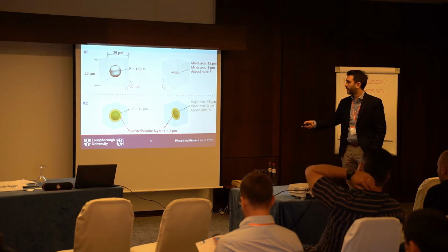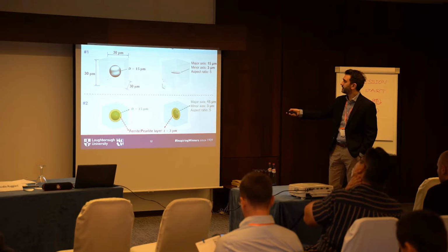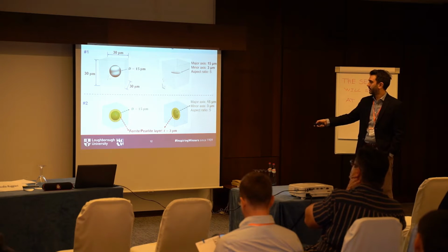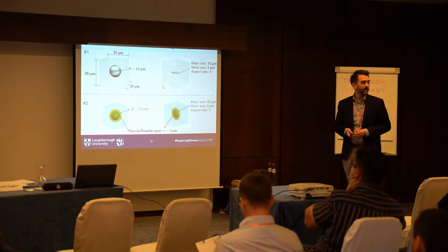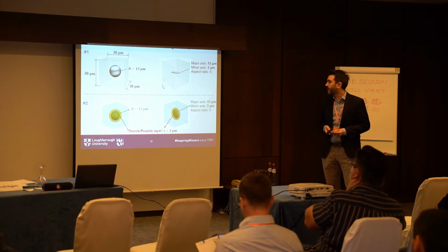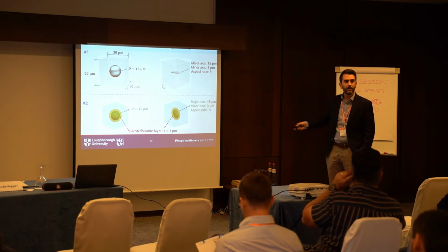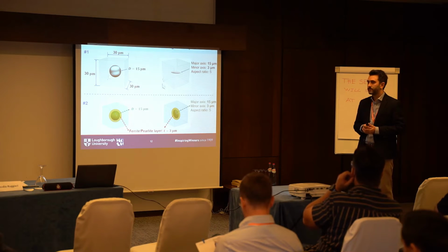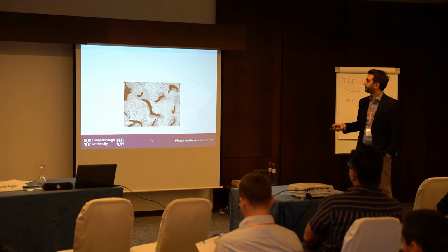The second model has this ring around it, okay? And you see this is the ellipsoid, this is the oblate spheroid, the oblate ellipse that I said earlier. They are somewhat different. So this ring around it is a ferrite or perlite layer. Why is that? Because we saw from the micrograph that these rings can form around inclusions, and area studies show that they can protect the inclusions from being damaged.